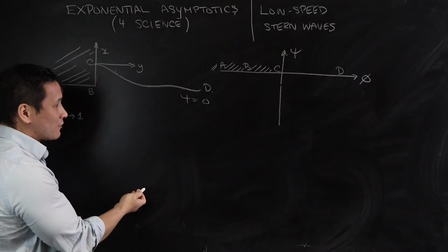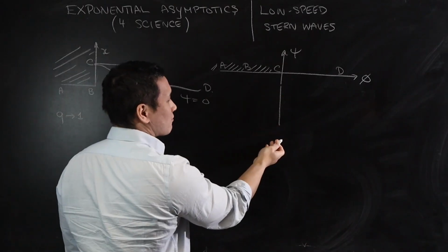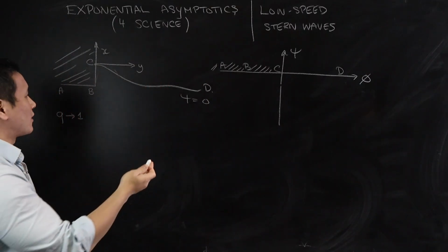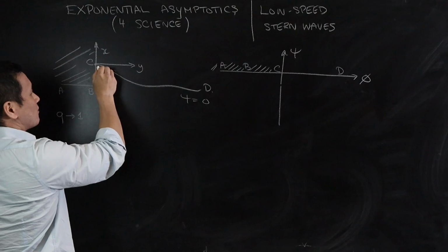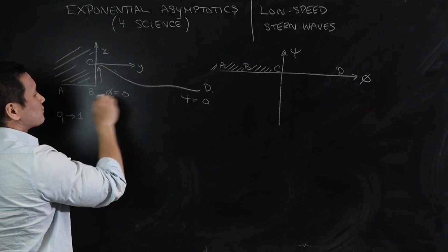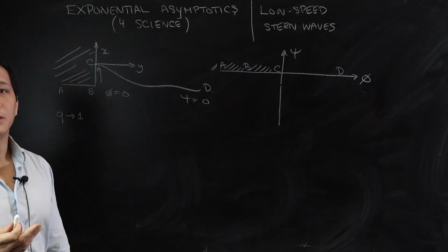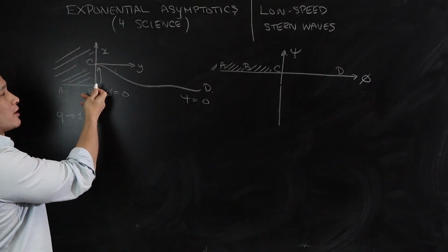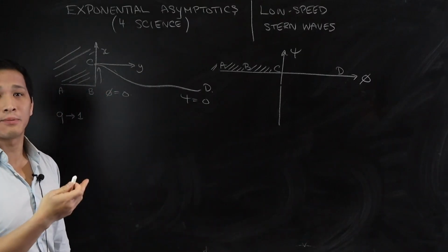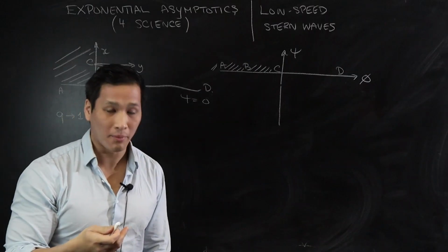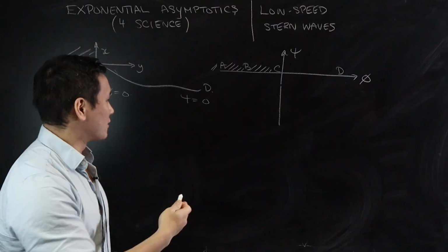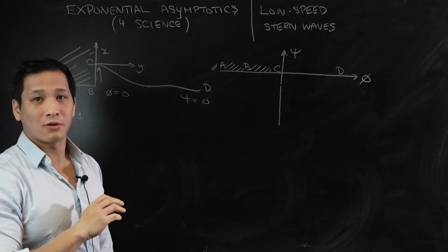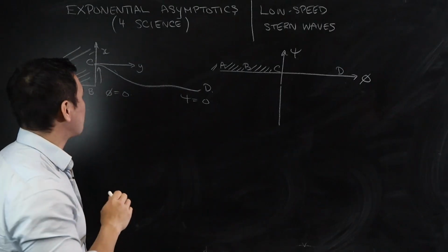Downstream, or infinite depth, would correspond to psi going to minus infinity. And then phi is effectively the coordinate that is 0 at the stagnation point. Phi is equal to 0 here. You also need to introduce a coordinate for the corner point here. So we're going to assume that the shape or the body of our ship is going to be in this rectangular form with an angle of pi by 2. But then actually we can do all sorts of different angles in a minute.